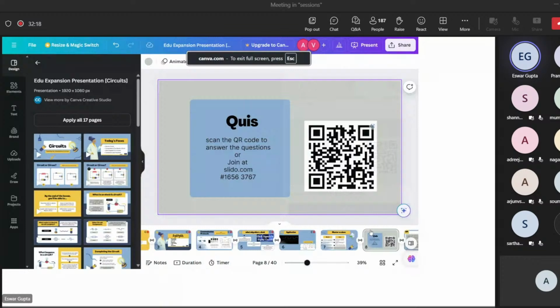SPI is a communication protocol which is used if there is one master and multiple slaves. How does this work? It mainly has 4 lines, 3 lines mainly. One is the clock, that is SCK. That is what I said, a clock must be there between 2 devices for communication. Another is MISO. The name itself suggests master in, slave out. That is, the master will get data in, and the slave will send the data out.